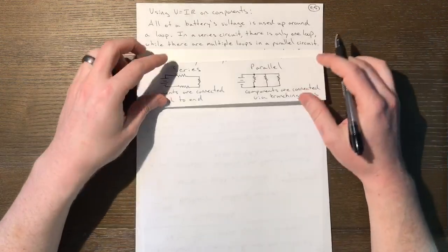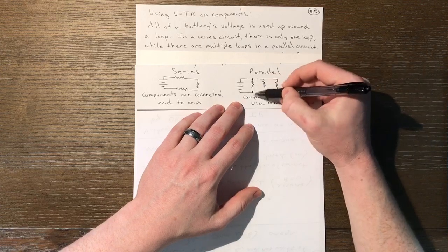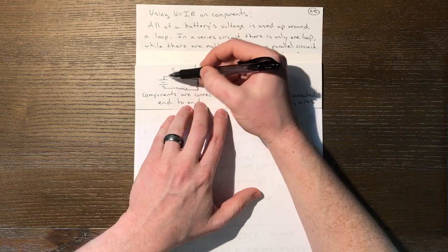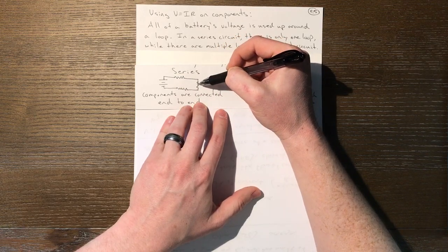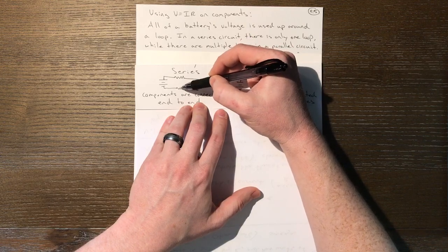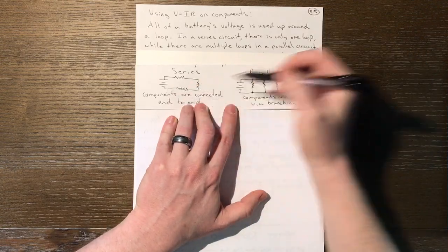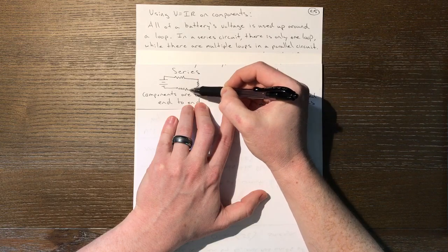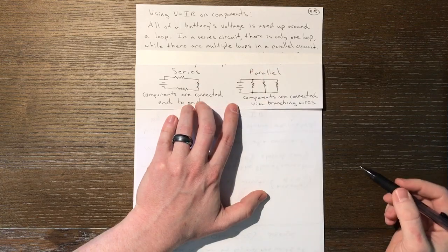Now this actually is why, in parallel circuits, the voltage drop across each is the same. So if we're going to spend all our voltage, say we've got a 12-volt battery here, we could leave it, spend 2 there, then spend 4 there. That's 6 total. We need to spend 6 more. It means we use up our remaining 6 on that last resistor to make sure we've spent all 12 volts by the time we get back to the battery. So we leave with 12, we spend 2, we're down to 10, spend 4, we're down to 6, spend the rest, 6, down to 0. We get back to 0 by the end of our loop.